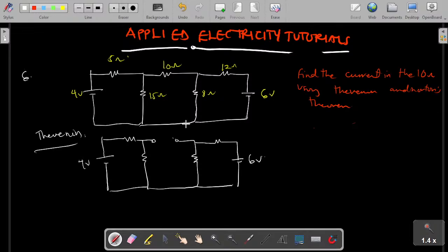This 4 volts. So now we've been able to remove the resistor, and what Thevenin says is that once you remove your resistor, the next thing is you introduce an open circuit voltage VTH, a special voltage, and assign it a direction. So we assume that there is a voltage source here, just an assumption, with a direction pointing this way. Remember, this voltage source is pointing up. So whenever you have a voltage source, where is the direction your current is flowing? You need to know.